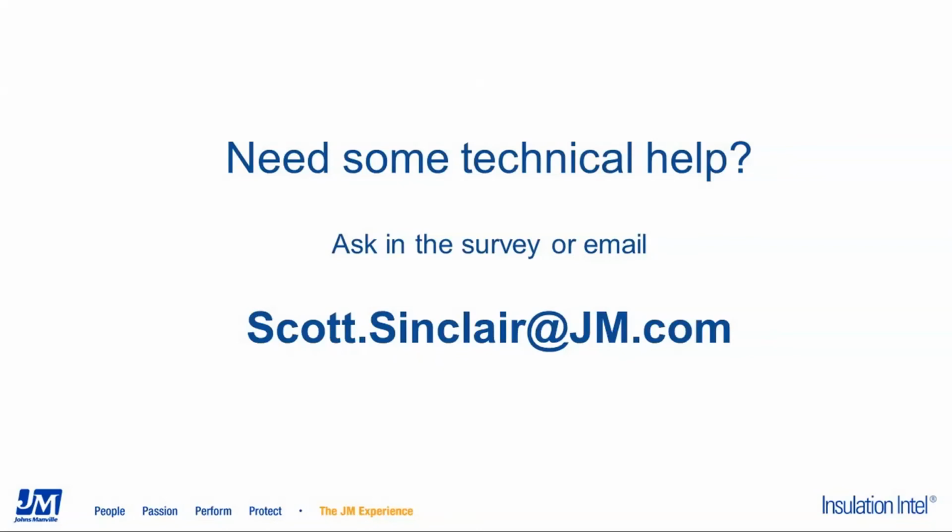A couple more questions for the team. Is the approach for preventing CUI the same for low temperature piping systems as it is for high temperature piping systems? Which goes back to the cryogenic questions. Well, typically the risk of corrosion on low temperature systems is much lower, as has been pointed out in one of the previous questions. Most people consider the high risk corrosion zone to be the temperature range from somewhere around 50 or 60 degrees Fahrenheit up to about 300 degrees Fahrenheit. Cyclic systems, so systems that may operate at higher temperatures than that but cycle in and out of that corrosion zone band, are the ones where you really have the biggest risk of corrosion under insulation.